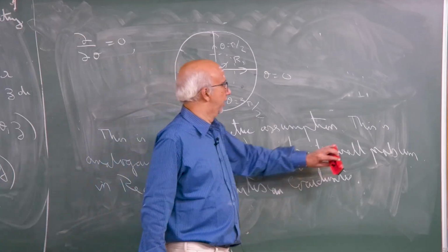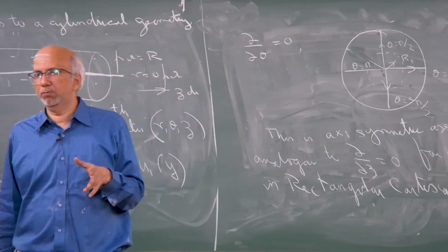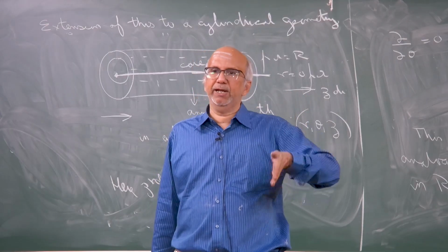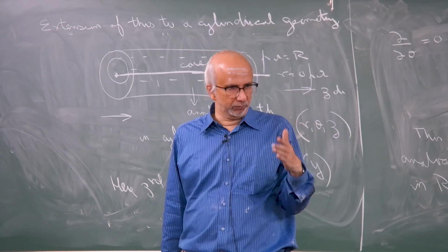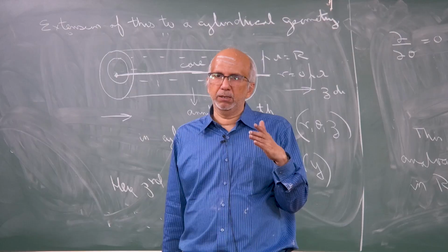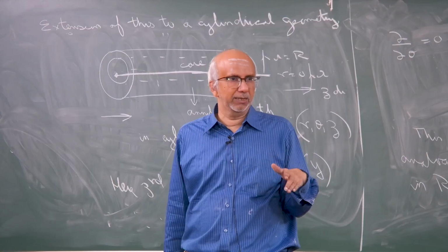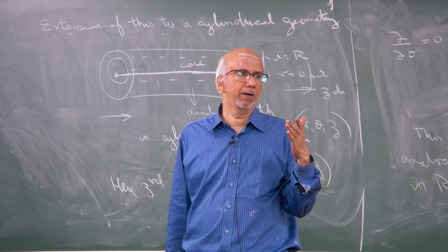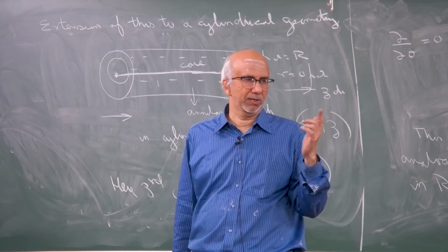So, again this problem is also a one dimensional flow problem, where you have only one dominant velocity component varying in a direction perpendicular to it. If you were to simplify the equation of continuity and the equation of momentum like we did, you will get similar simplified equations which you should be able to integrate and find what the velocity profile is, and find what the flow rates are as a function of capital R1, small r, and capital R.